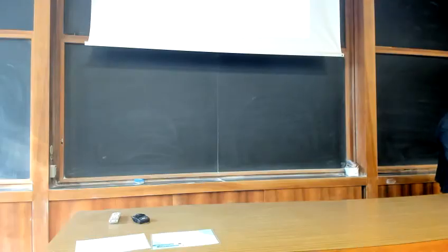And so you have a sort of softening behavior. You have a reduction of the load sustained by your footing. But in order to generate this mechanism, you have to reach this peak load. And this will definitely be our bearing limit. This is clearly defined. So when we think of a general shear failure, we are looking for this value, for this peak load.